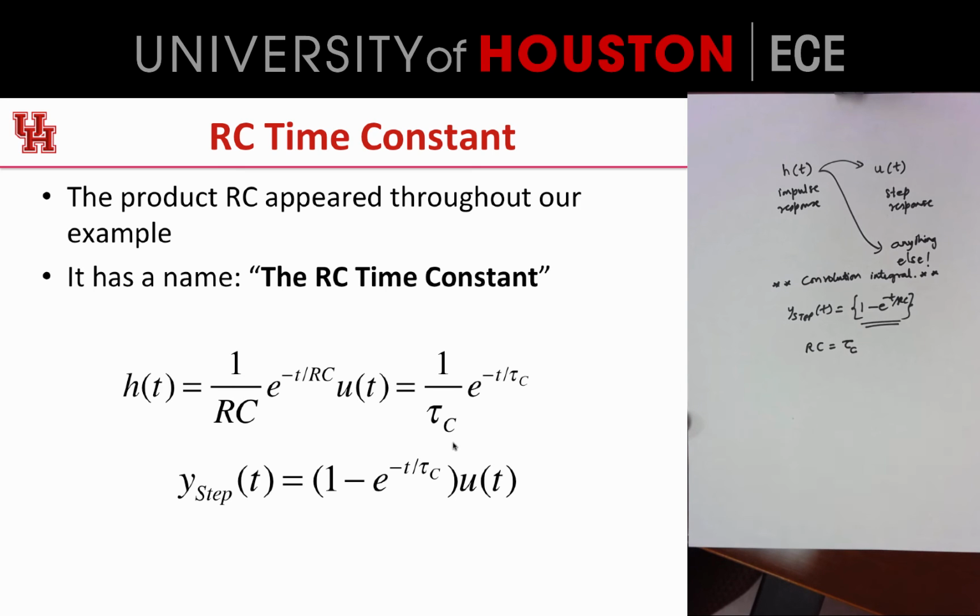And at the same time, if you have even a small capacitor but a very high resistance, so the capacitor charges very slowly, then you're going to have a large time constant, right? Therefore, it makes sense that the product of R and C defines the time constant. Okay? If the capacitor is big, it charges slowly. If the resistor is very big, it also charges the capacitor slowly.